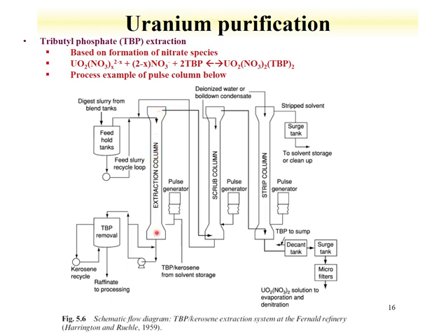The aqueous phase goes here, the organic phase containing the uranium here. The organic phase is taken and added to the scrub column, so this could be the same concentration of acid, let's say 3.5 molar. As the organic bubbles float up, any metal ions that aren't the uranium can be preferentially removed. The uranium preferentially stays in the organic phase. This organic phase is then transported to a strip column. This contains a lower acid concentration. The tributyl phosphate moves up and leaves behind the uranium in the aqueous phase, in which the uranium can then be collected and formed into uranyl nitrate.